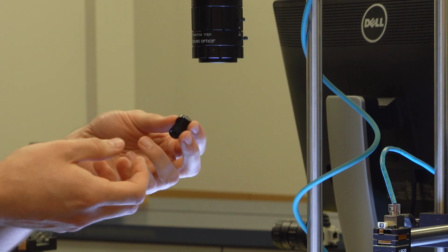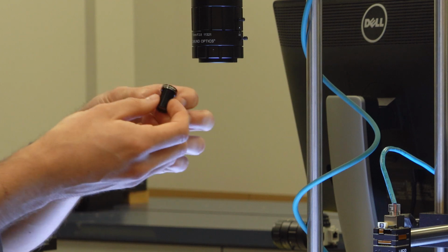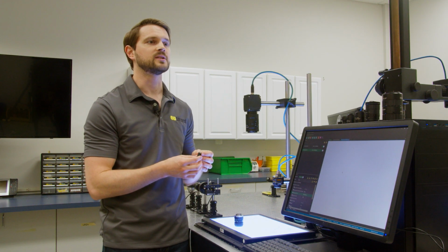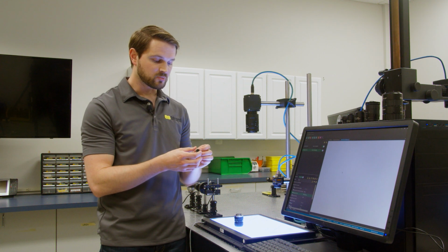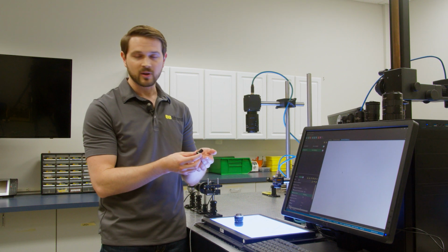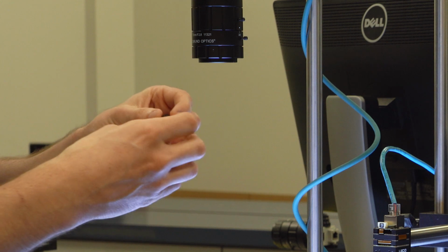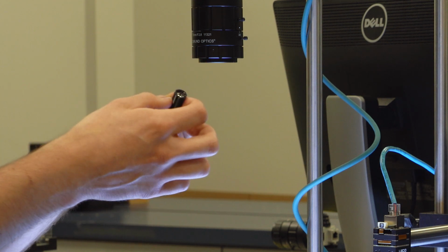These are used for lightweight or small applications. It makes sense, it's a small, lightweight lens. So they're used a lot in drones, document scanners, biometrics, things like this. They're pretty high resolution little guys, but as you can imagine, they're relatively feature simple. They don't have any sort of iris adjustment. You focus them by threading them in and out of their barrel, and there's no real way to lock it down.